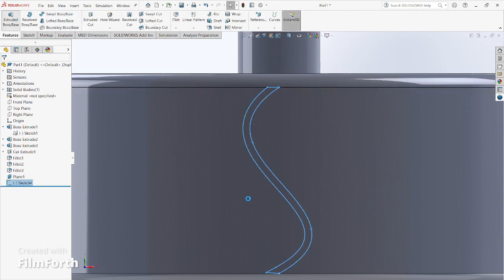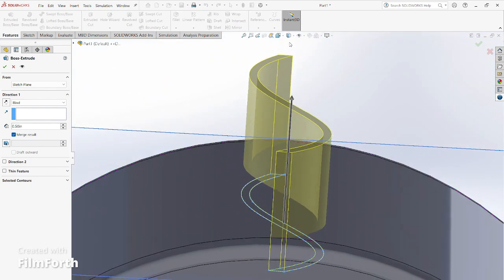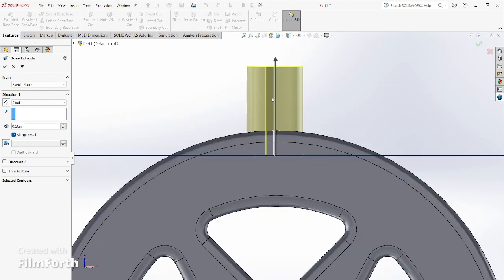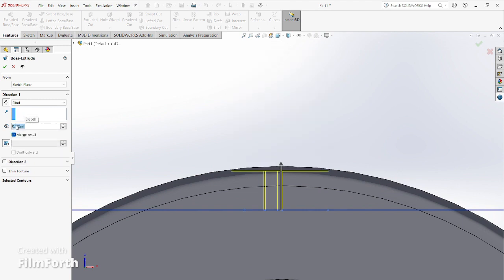And then what I'm going to do is extrude it upward. There we go. So now we're going to be careful on this right here. We need to know how far our treads have to go. So it's going to be about 0.5. I'm going to put like 0.125. Depends how thick it is. Okay, that's a little too small. So let's try using the arrows. 0.225 and 0.125.